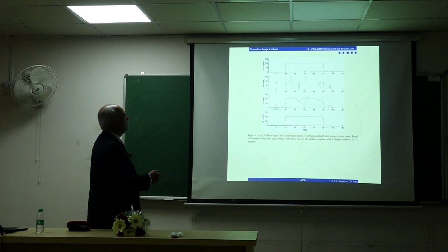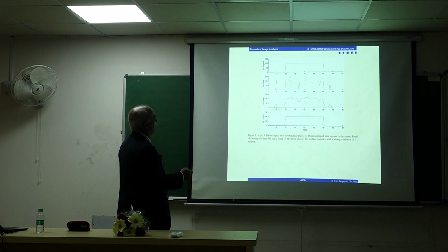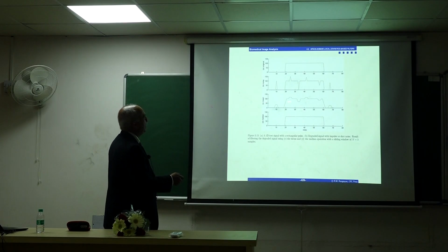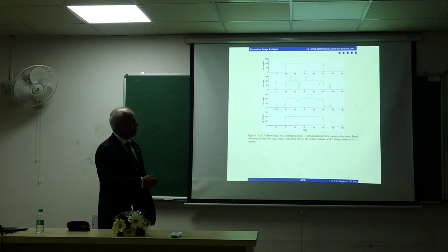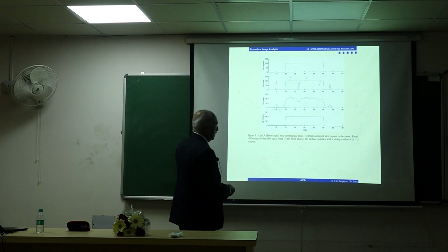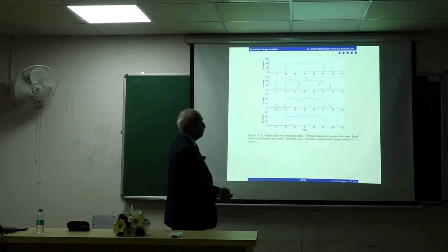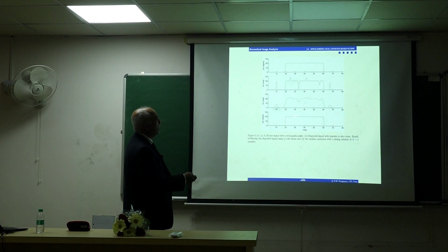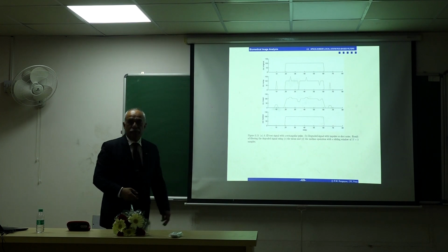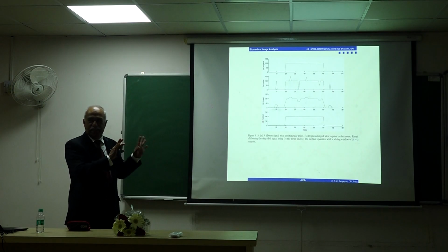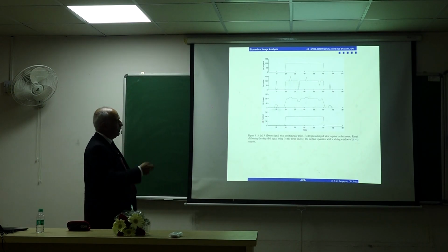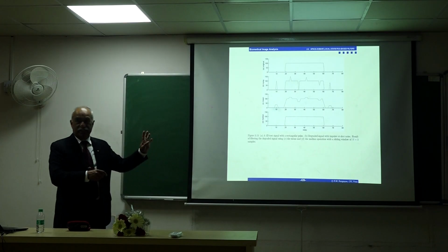So here's a simple example with a 1D signal, just a block here, a rectangle, and I added some spike noise, salt and pepper noise, to that. And if we apply the mean, you get this, which is not very good. The mean filter was applied with n equal to 3 samples. If you apply the median, you get the original back. But this is a synthesized example, a made-up example, but it shows how median is better than mean in such cases.